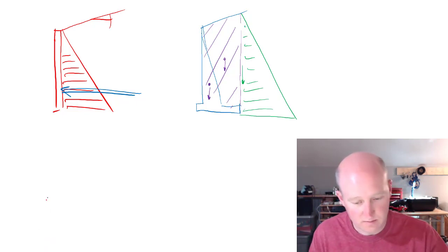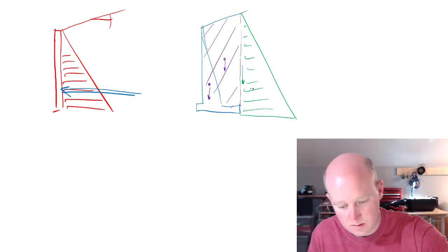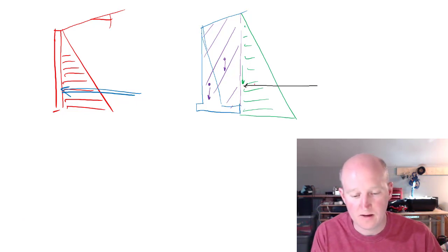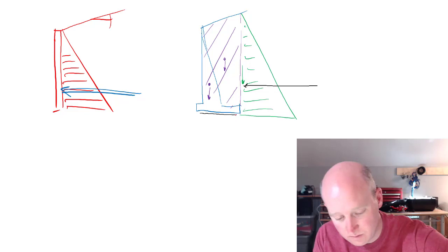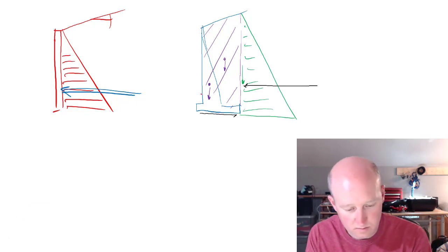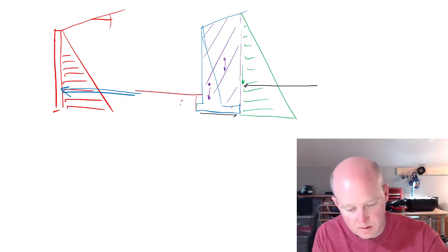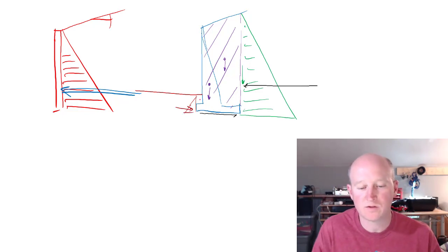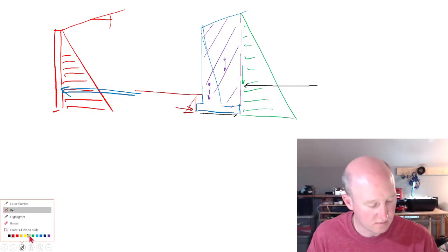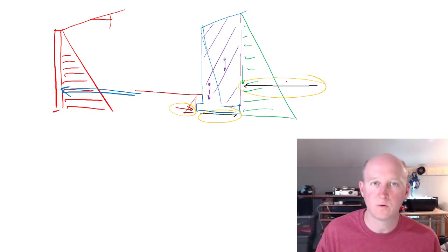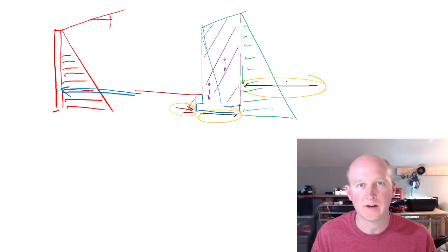We would also have a horizontal force from the soil, and then there would also be a frictional force at the bottom. And maybe if this material was embedded, there would also be a pressure distribution at the toe with a corresponding resultant. And we would sum all of these horizontal forces in the x direction, and we would look at the driving forces and the resisting forces, and we'll come up with a factor of safety based on that. The other failure mechanism